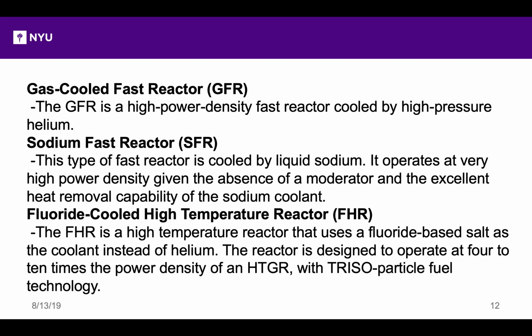The gas-cooled fast reactor is a high power density fast reactor cooled by high pressure helium. The sodium fast reactor is a type of fast reactor cooled by liquid sodium. It operates at a very high power density given the absence of moderator and the excellent heat removal capacity of the sodium coolant. Most of the designs under consideration today are small SFRs that have inherent and passive safety features that may not be viable in large sodium systems. These concepts have the potential to reduce cost but require additional technology development.